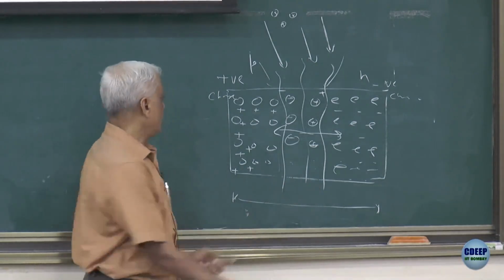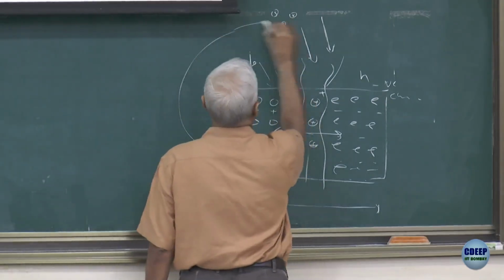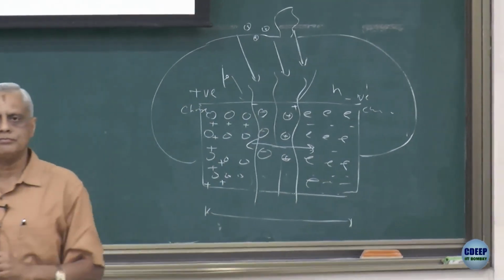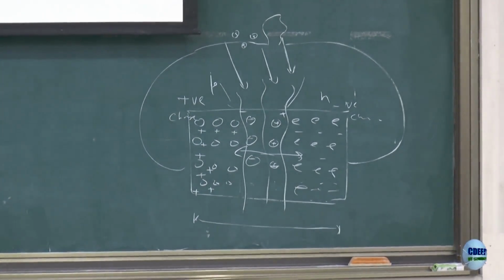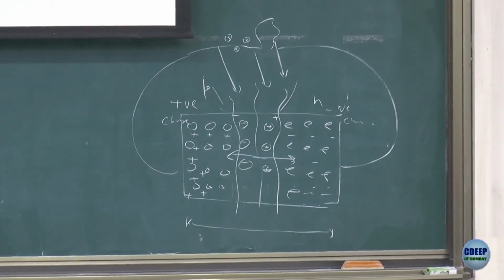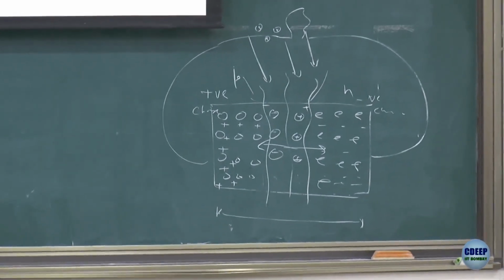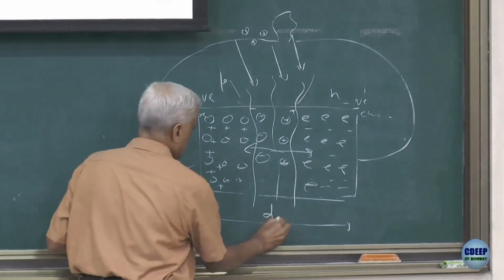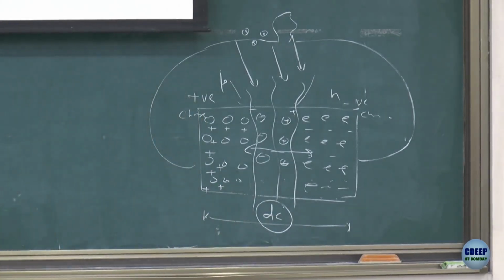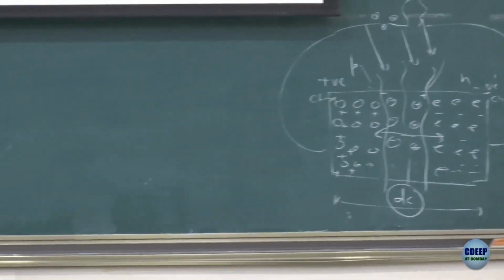And now if you connect any load across it, let's say a bulb, then this bulb will glow if it is of appropriate voltage and current levels it can provide. This is how a solar PV cell would work. The point to note is that this is DC. What you get at the output of the PV terminals, module terminals, panel terminals, is all DC.